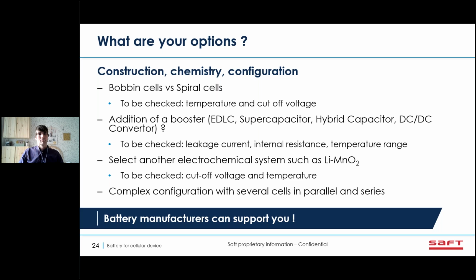You can add a booster to the cell: supercap, EDLC, hybrid capacitor, DC-DC converter, whatever, many different kinds of possibilities. But for this, you will need to check the leakage current of the additional component you add, because it will reduce your life duration. You need to check the internal resistance of this additional booster and the temperature range.